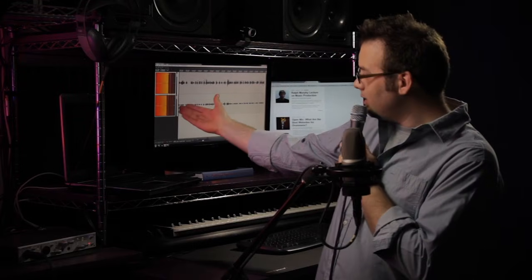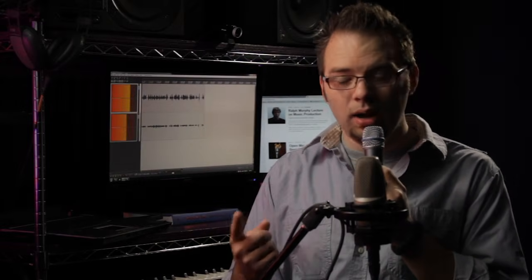It's still not as hot as this condenser microphone, but that's just because this microphone doesn't have as great of an output, and it's also running through a different preamp, which has a different gain structure, so the two levels are not exactly comparable. But you can see that the level we have to work with, now that it's running through a microphone preamp, is much greater, and we have a lot more flexibility, a lot cleaner of a signal to work with, and we'll get a lot less noise in our recording. So, microphone preamp with the microphone, always the way to go.